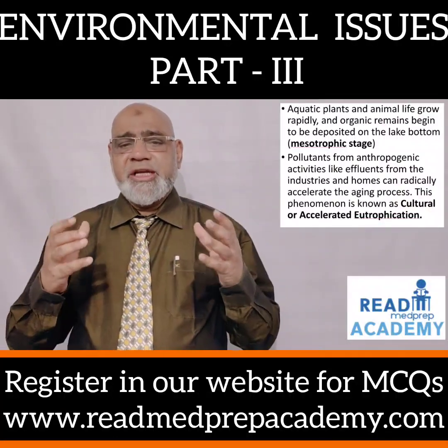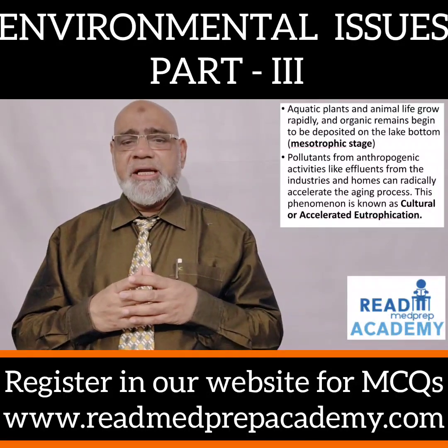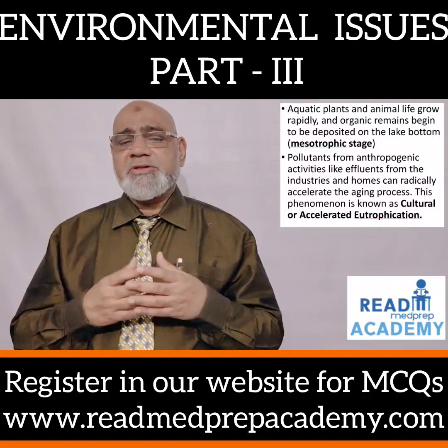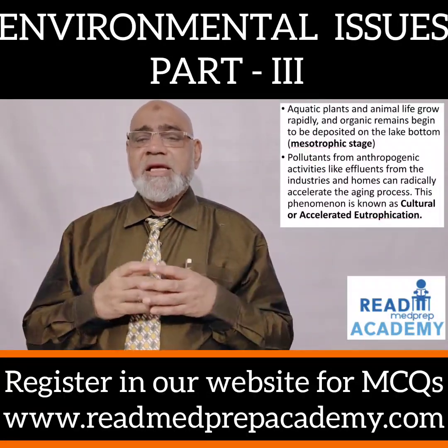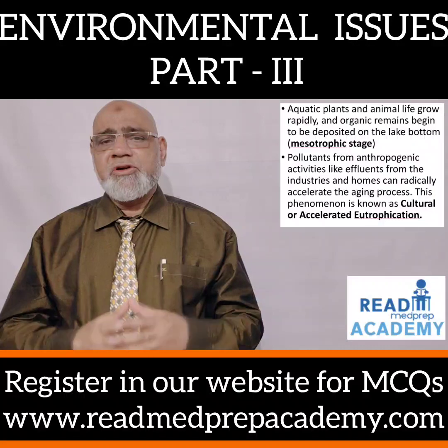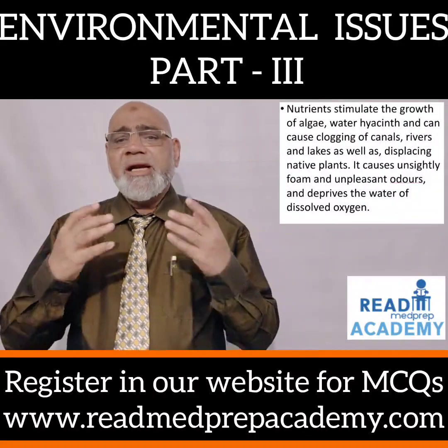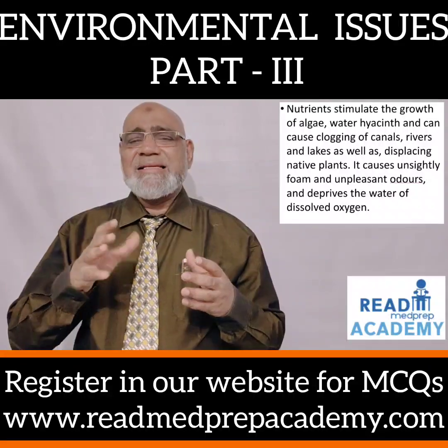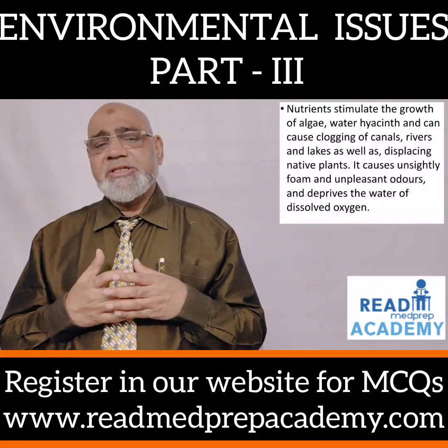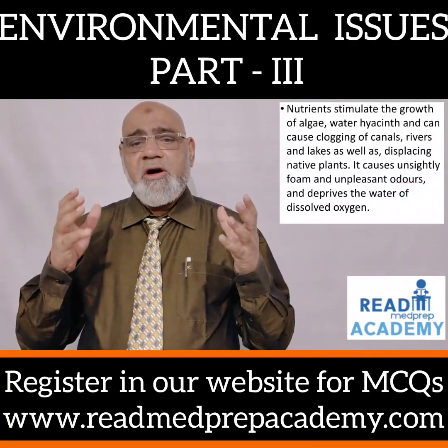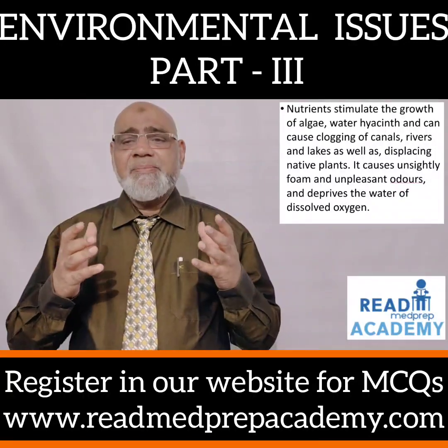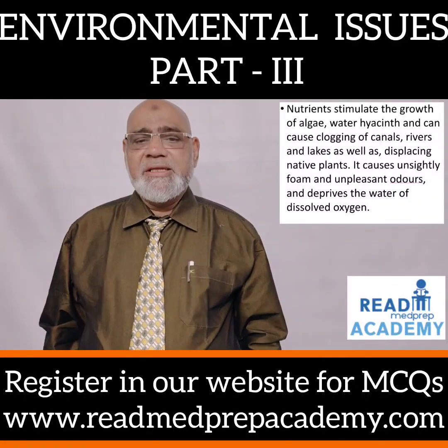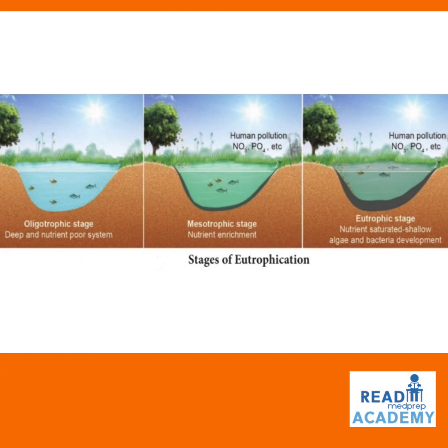Pollutants from anthropogenic activities like effluents from the industries and homes can radically accelerate the aging process. This phenomenon is known as cultural or accelerated eutrophication. Nutrients stimulate the growth of algae and water hyacinth, and can cause clogging of the canals, rivers, and lakes, as well as displacing native plants. It causes unsightly foam and unpleasant odors and deprives the water of dissolved oxygen for other animals. Here you can see the stages of eutrophication.